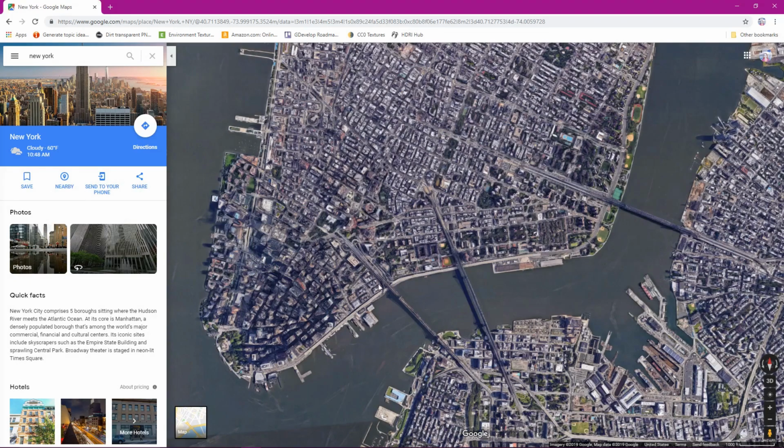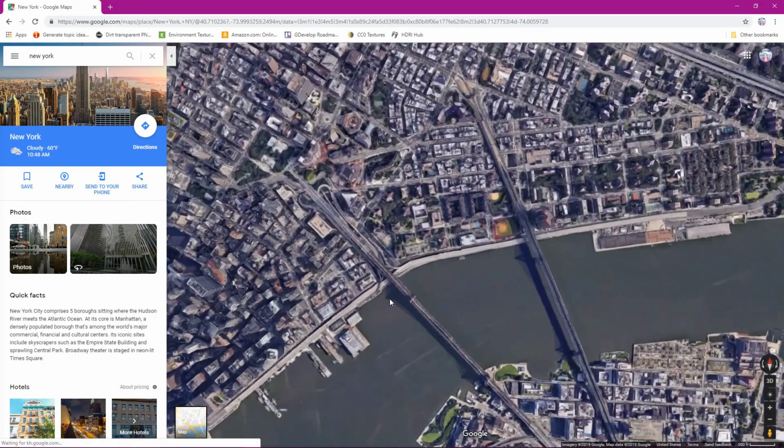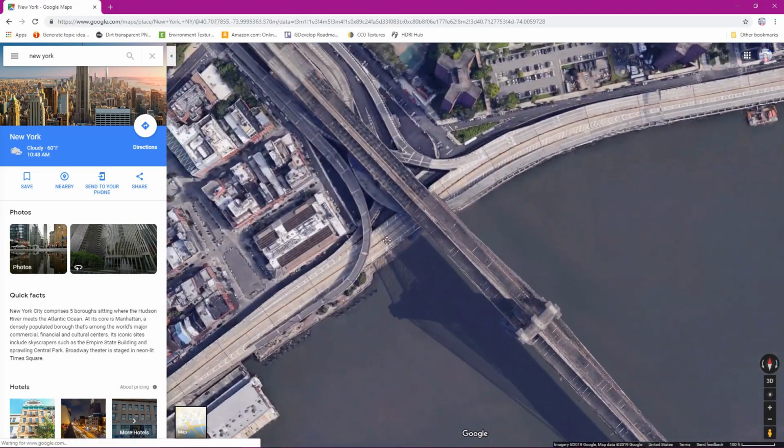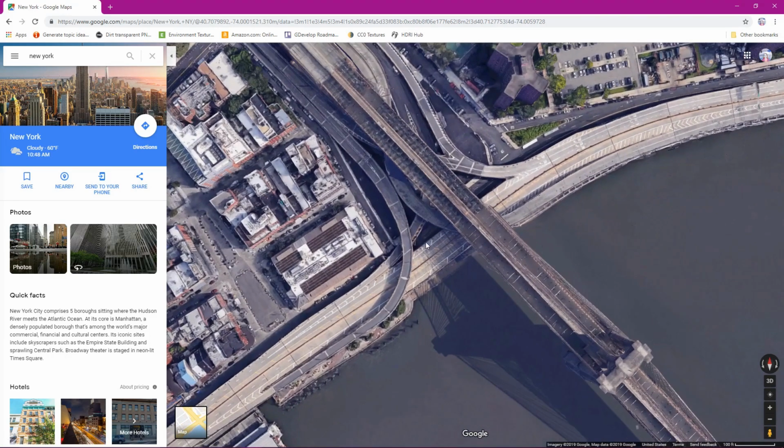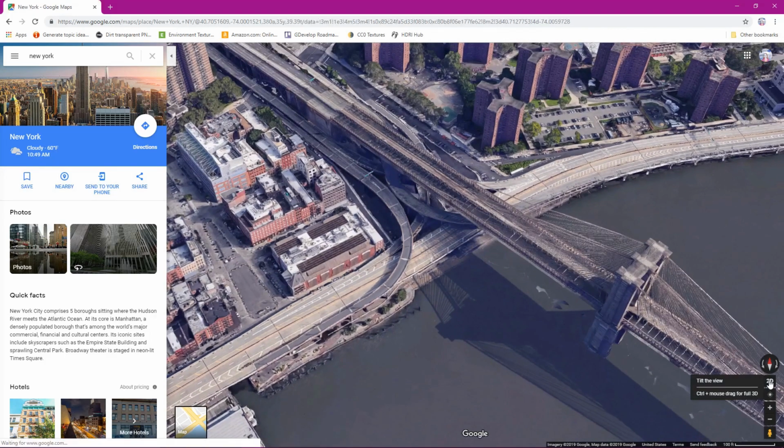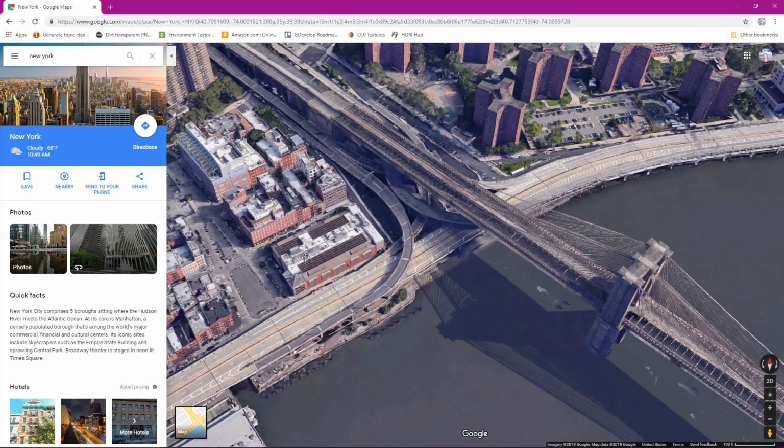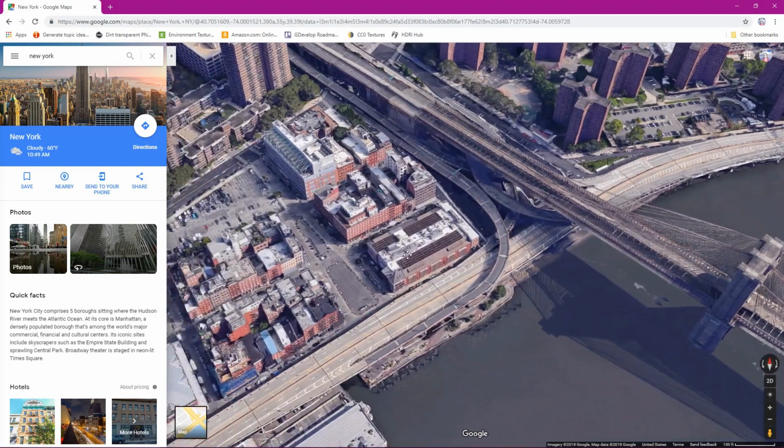So now what we want to do is, I'm looking at this area right here. I'm going to zoom in, right? So we have this top-down view, not quite isometric. However, look to your lower right. See this thing that says 3D? We're going to left click here. And now you can see we have this isometric-like view here.